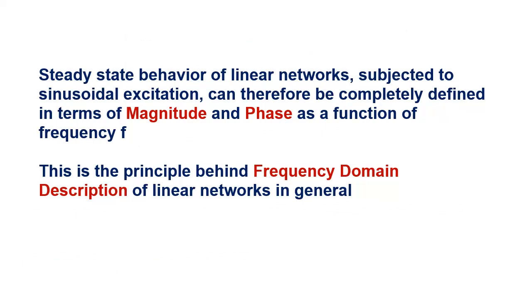Steady-state behavior of linear networks, subjected to sinusoidal excitation, can therefore be completely defined in terms of magnitude and phase as a function of frequency. This is the principle behind frequency domain description of a linear network.